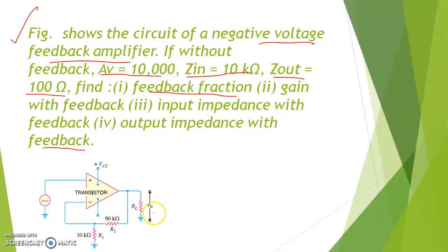See, we are taking the output voltage Eoutput across RL. So this will be plus, this will be minus, and see, the feedback network is basically this one. You know from the concept of practical feedback network, I have already discussed this circuit. So this is basically the feedback network. Okay, so you can say this generates the beta or feedback factor. So see, the starting point of the feedback network on the output side and the output voltage are at the same node. So this is basically voltage sampling.